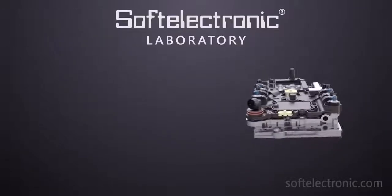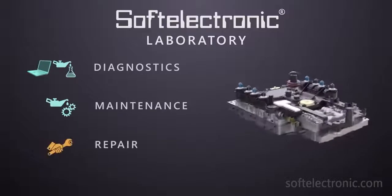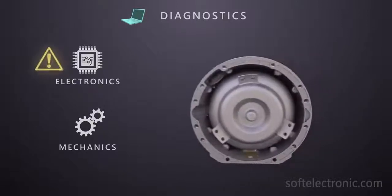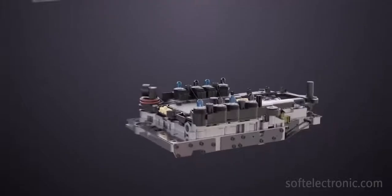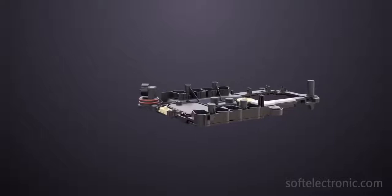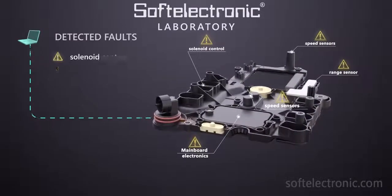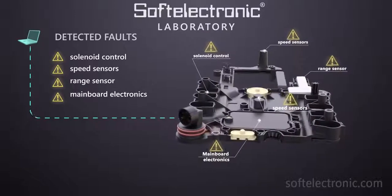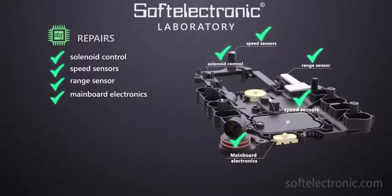In the soft electronic workshop, vehicles can get proper diagnostics, maintenance, and repair of the components in the mechatronic. If the automatic transmission is diagnosed with a problem in the electronics, the mechatronic must be dismantled from the gearbox and the control unit separated from the valve body. After that, it proceeds to the soft electronic laboratory where it's fully inspected. The client is informed on the status of the unit and the repair costs. Upon the client's approval, the necessary procedures are performed to have the mechatronic restored to its factory specifications.